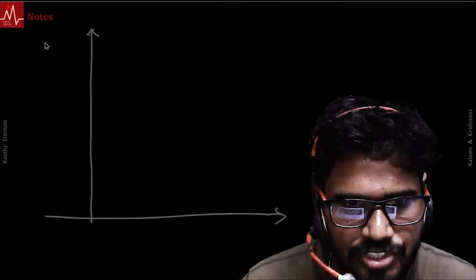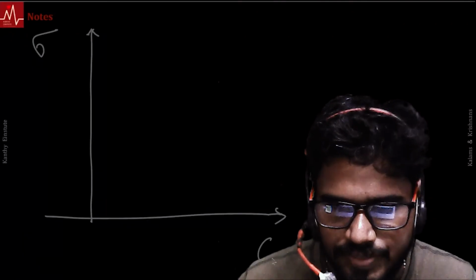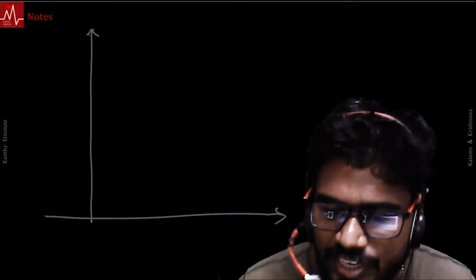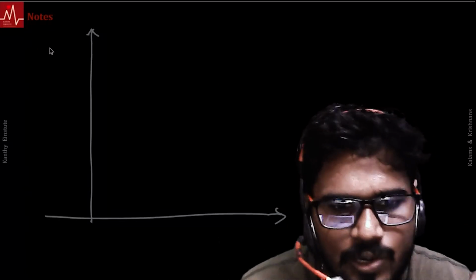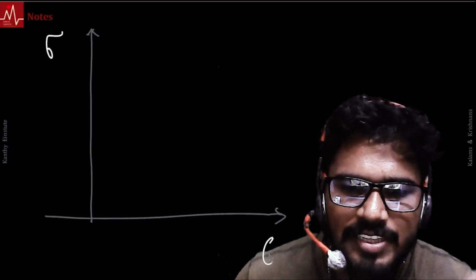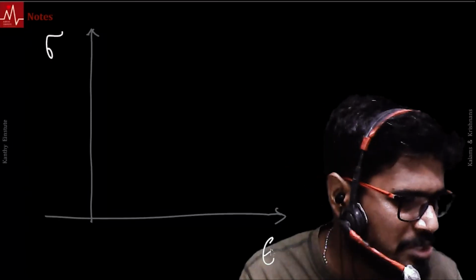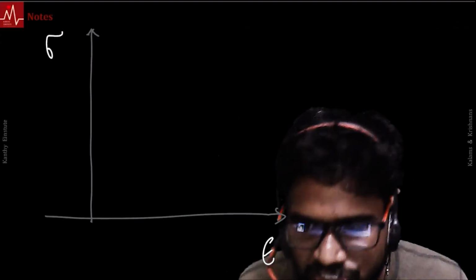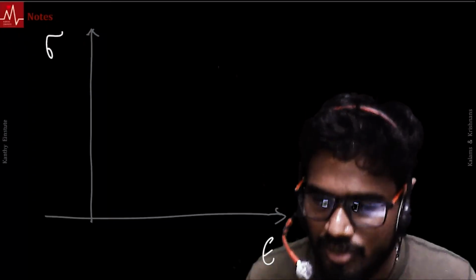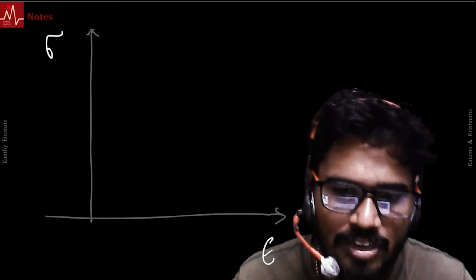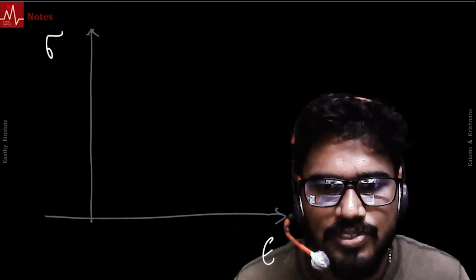Summary: you're plotting stress and strain. Often we are looking at stress strain as independent of geometry. Load versus deflection is dependent on geometry. This is a property that is independent of geometry. You do one experiment, and you can apply that to any geometry. On the other hand, if you're plotting load versus deflection, for each geometry you're doing an experiment. There are infinite geometries, right? You run into this issue.